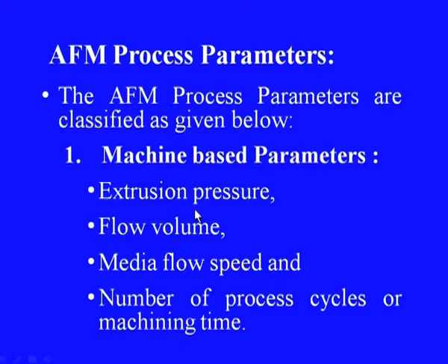The machine based parameters include the following: extrusion pressure, flow volume, media flow speed and number of process cycles or machining time. In most of the published literature, the number of process cycles is reported. However, this can be equated with machining time, which is not used so frequently so far.